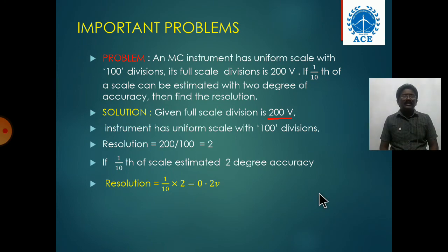With the help of the shunt type ohm meter, you can measure resistance in ohms. Here also you have to take help of the calibration of the shunt type ohm meter, so that you can calculate the unknown resistance.